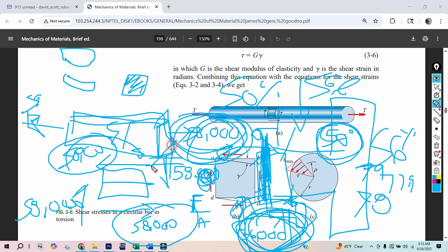But these forces are getting applied at a 45-degree angle, so you only get a square root 2 of them. You only get like a 1.4, and then maybe inverse 1.4, and you get like a 0.7. 0.707, that might get you closer. But the actual Poisson's ratio, if you do the math from this textbook, you get 0.78, I think. I think it's like 0.79. If you actually do it.